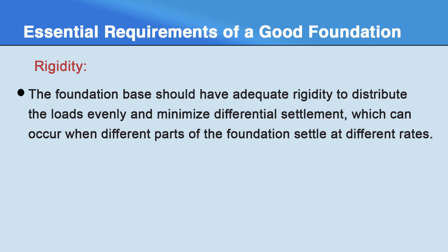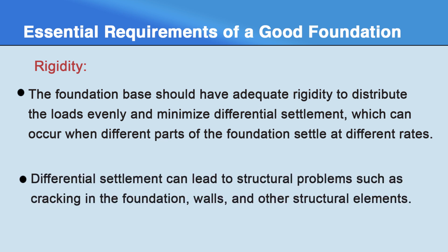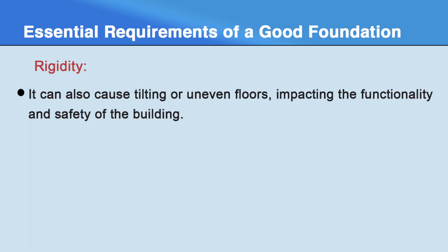The foundation base should have adequate rigidity to distribute the loads evenly and minimize differential settlement, which can occur when different parts of the foundation settle at different rates. Differential settlement can lead to structural problems such as cracking in the foundation, walls and other structural elements. It can also cause tilting or uneven floors, impacting the functionality and safety of the building. Ensuring the foundation is designed with enough stiffness and strength to resist deformation.